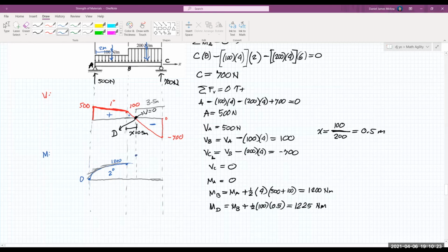The moment is approximately here. Okay, so similarly, for the slopes here, the shear from B to D goes from 100 to 0, so that's decreasing. So the slope of the moment diagram should also be decreasing, from vertical to horizontal, approximately, so it will look like this.